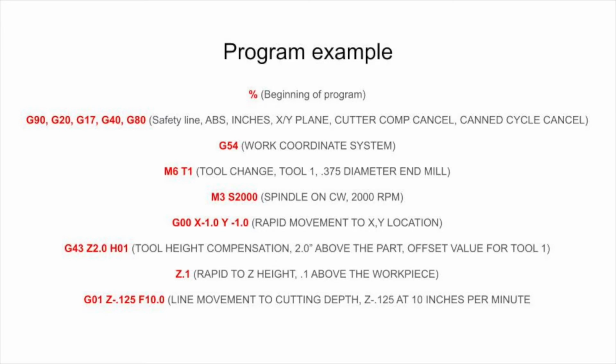So we are away from the workpiece. We're dropping down to a negative Z depth by using our G01 code, and then we'll be engaging our workpiece with the rest of the line movements after that. The following video will be discussing a couple options to cut our desired workpieces. The first one is to factor in the radius of the tool and move to that position. And then the second option will be using cutter compensation.